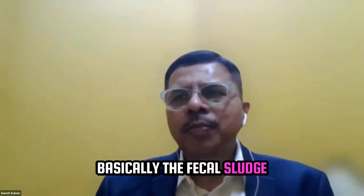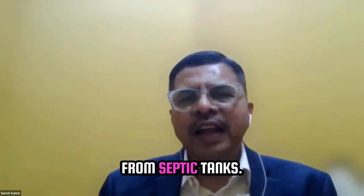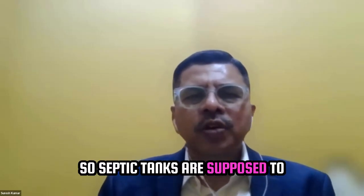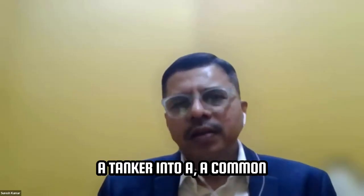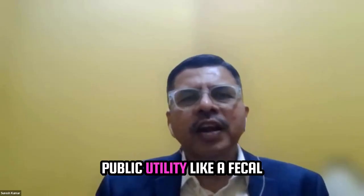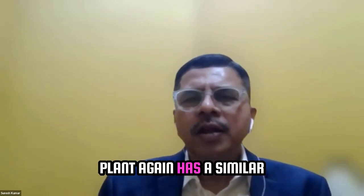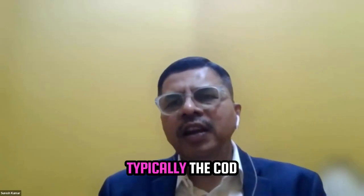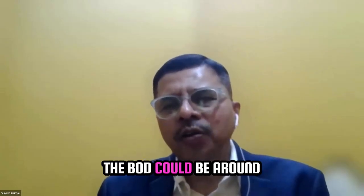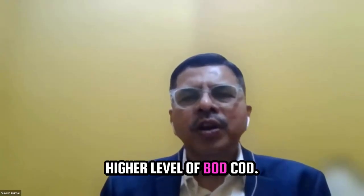Basically, the fecal sludge treatment plant is supposed to get sewage through tankers from septic tanks. So septic tanks are supposed to discharge their sludge through a tanker into a common public utility like a fecal sludge treatment plant. It again has a similar treatment plant, but the BOD COD values are much higher. Typically, the COD is around 5,000. The BOD could be around 3,000 to 3,500. So you need to plan for higher levels of BOD COD.